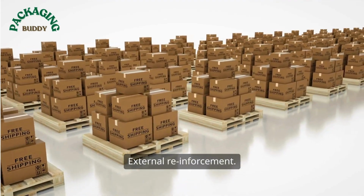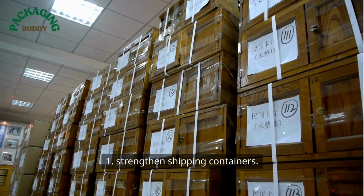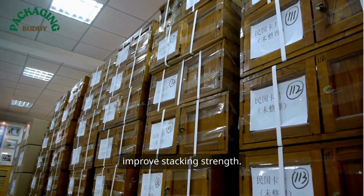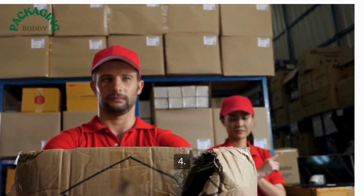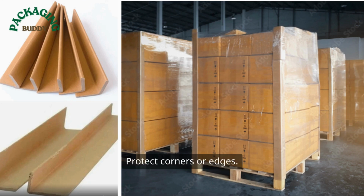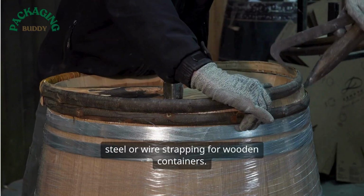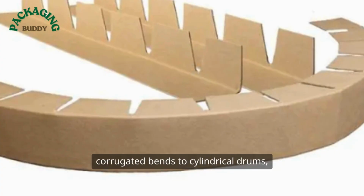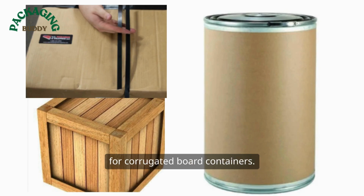F. External reinforcement. External reinforcement is required to: 1. Strengthen shipping containers. 2. Improve stacking strength. 3. Avoid bursting. 4. Increase weight carrying capacity. 5. Protect corners or edges. External reinforcement can be achieved by providing wooden containers, steel or wire strapping for wooden containers, corrugated bands to cylindrical drums using edge protectors or steel corners, and PP straps for corrugated board containers.